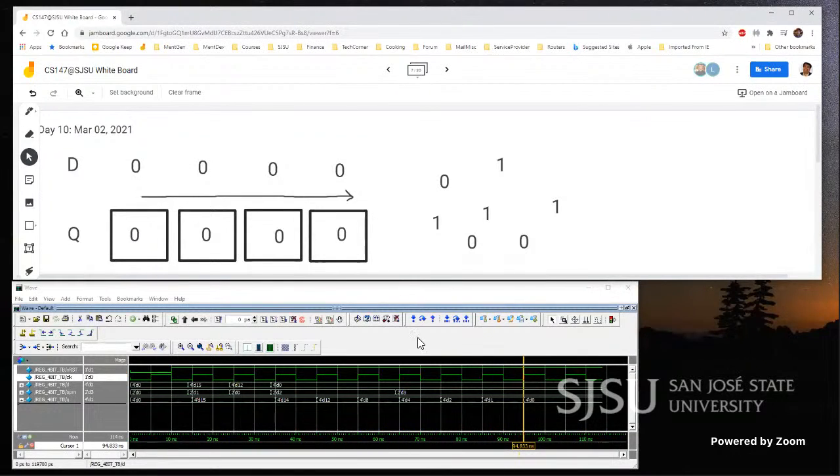Okay, so one observation to be made here in this operation is that the number of bits we want to shift is the same as the number of clocks we need to spend. So if it is a 4-bit shift, like from 8 to 0, it is a 4-bit shift operation. For that, we need to spend 4 clocks, so 4 times the clock time period. And that's where the combinational shifter comes into action. Combinational shifter, it's basically instantaneous.